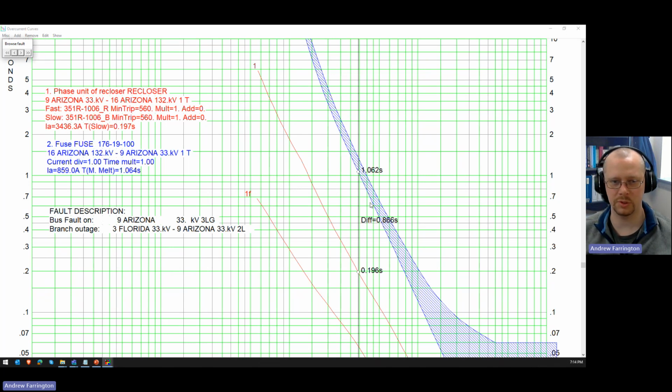And usually what you do is you don't include every plot that you run. You just include the worst case, and you say that this is the worst case CTI. And because this CTI is greater than, well, in this case, the minimum CTI is just clear space, you can say this proves that these two elements coordinate. You'd want to be more thorough in your approach for which outages to run than we just were. I just kind of picked some, but that's generally what you do.